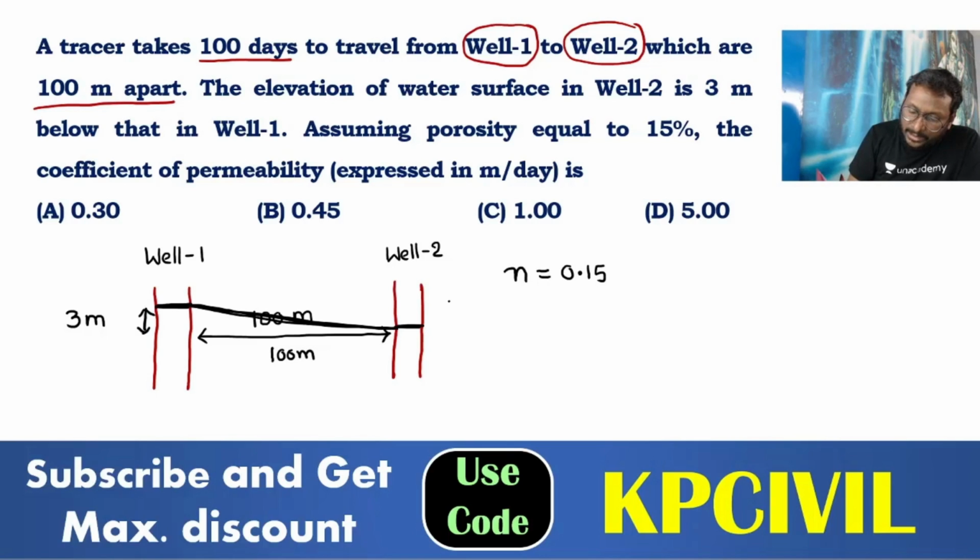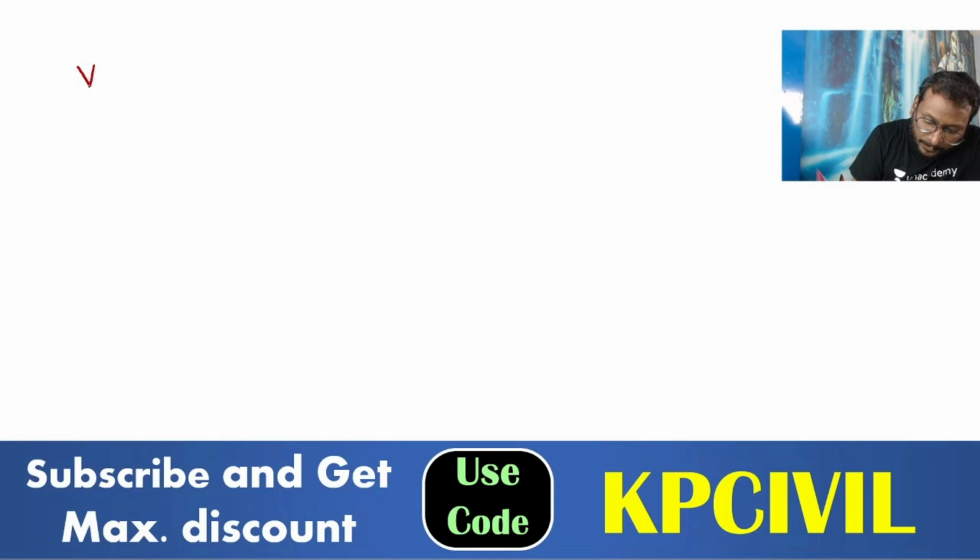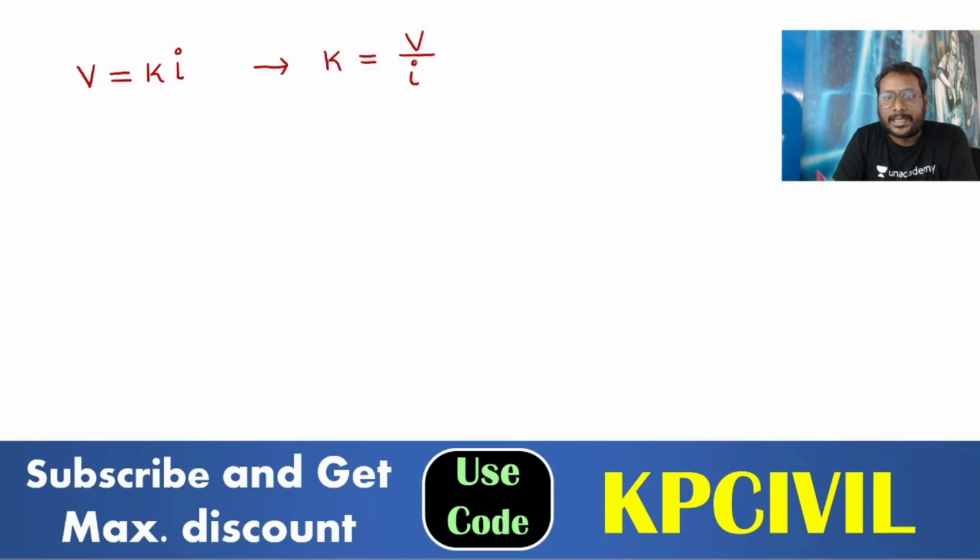The coefficient of permeability, K value, is how much? So you need the value of K, the coefficient of permeability. Take the continuity equation with respect to velocity: velocity is equal to K into I. From this, what can we write? Coefficient of permeability K is equal to velocity by hydraulic gradient I.